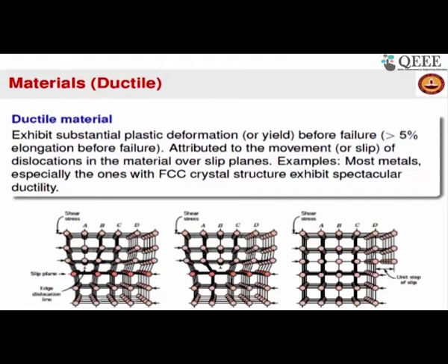So in the vicinity of that, near the region where the two planes basically come together like that, there will be some excessive stresses, and that particular defect in the crystal is called a dislocation. Okay, because the energies are high, when you actually apply a shear stress like what is shown in the second slide, this dislocation will slip.